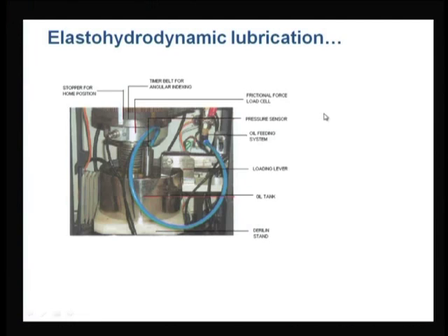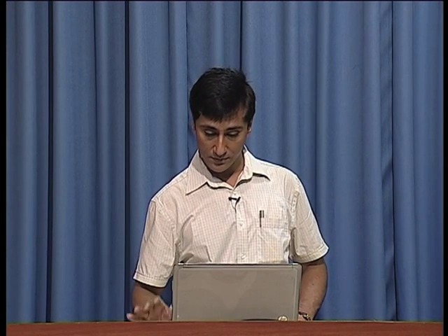That is why the pressure sensor comes, and this bearing rotates after a certain duration that can be fixed as per our own algorithm. At every 9 degrees it will rotate, or at every 9 degrees it will change its position after a certain duration. Maybe at time t equal to 0, it is at 0 degree. Maybe after time t equal to t1, it will rotate by 9 degrees and again it will stop. So, that we can cover the whole circumference to find out the pressure profile.